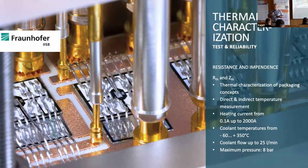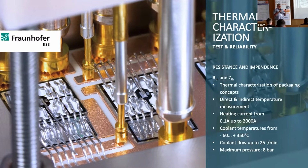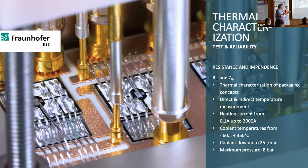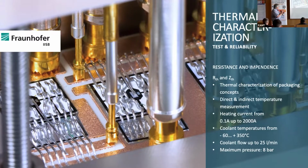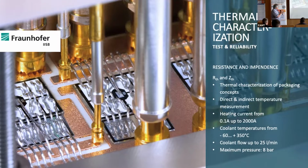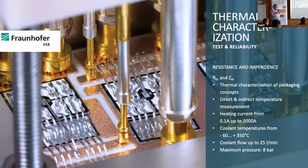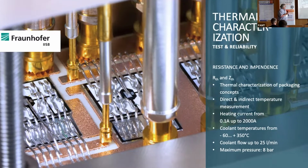And all I'm talking about is get rid of the heat and compensate for thermo-mechanic stresses, strains, and whatever, which may destroy your device. So one important part is thermal characterization. I don't go into the details. This is like a power system would look like. Normally you have a substrate, you have a chip on top, and believe it or not, we still have wire bonds a lot as a standard topside contact. The backside of the chip is typically soldered. And all these connections can fail if you do a lot of temperature cycling.